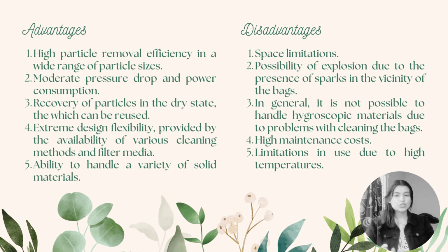Advantages: high particle removal efficiency in a wide range of particle sizes, moderate pressure drop and power consumption, and an ability to handle a variety of solid materials. In the disadvantages, we find space limitation, high maintenance cost, limitations in use due to high temperatures, and in general, it is not possible to handle hygroscopic materials due to problems with cleaning the bags.